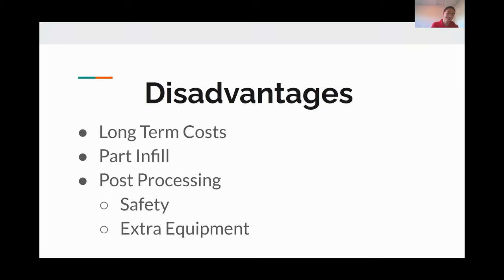This gets pretty complex. The sun emits three types of light: UVA, UVB, and UVC light. What cures the resin is UVA light, but the sun emits a lot more UVC light, which actually damages the resin. So normally you want a UV flashlight or a UV light enclosure to cure it, because those usually only emit UVA light and will make the part a lot stronger, while the sun could make the part even weaker.